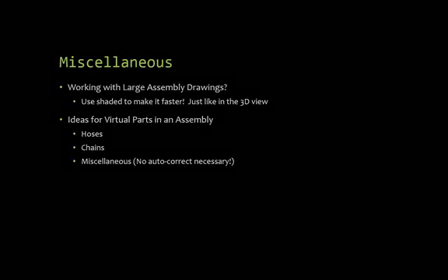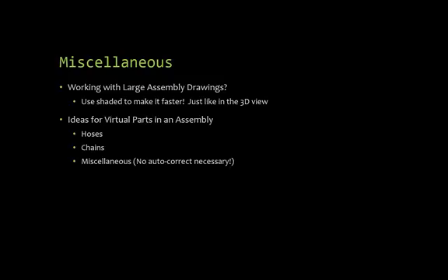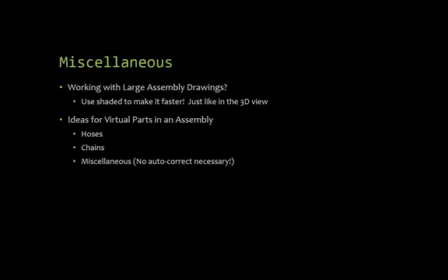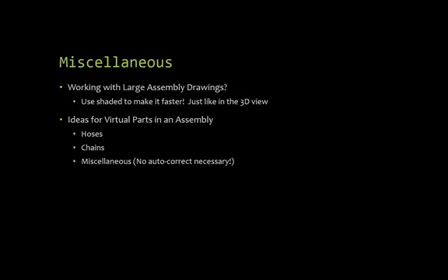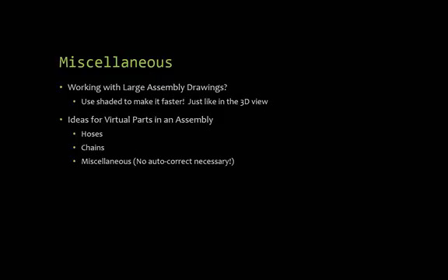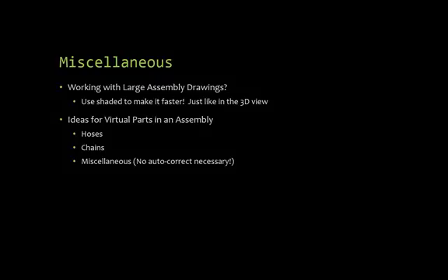So the first thing I did was I just hid them, so the graphics weren't being generated. That was night and day. And I said, okay, well, here's something else we can do. I turned them on, it slowed down again, and then I just picked the view, said make shaded, and got all my speed back instantaneously. Because even though there was a lot more geometry, the shaded worked a lot quicker, a lot better.